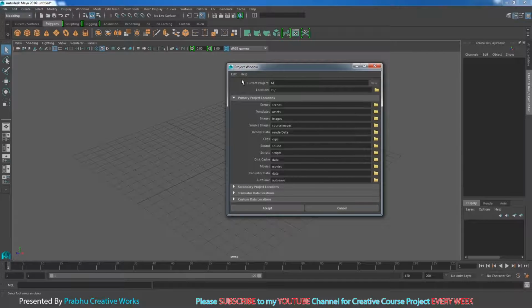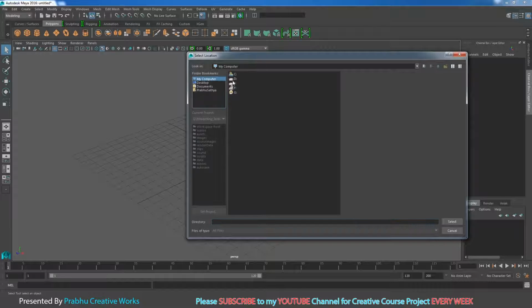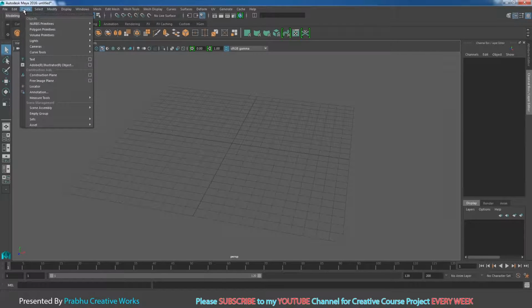So I will rename my project mobile_advertisement. I will choose my D drive. You choose wherever you want. So I give accept. Now I want to go over to the create panel, polygon primitives, and disable the interactive creation.